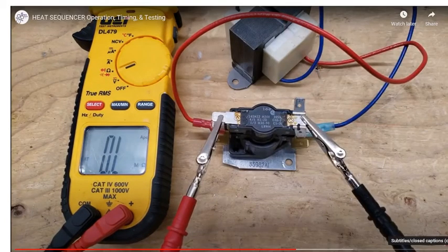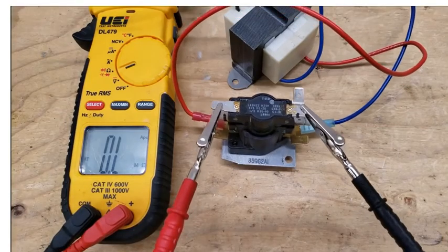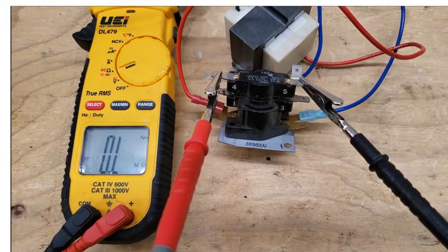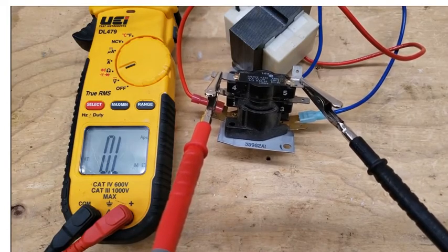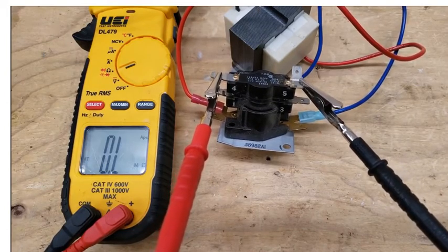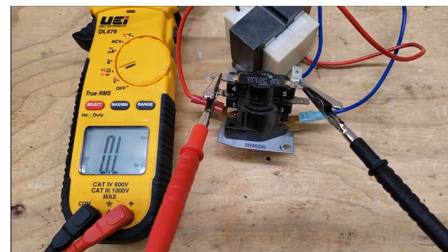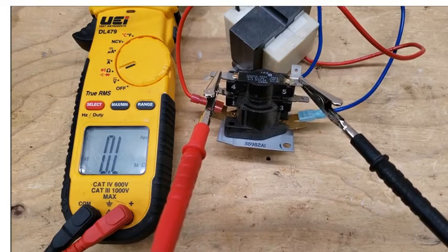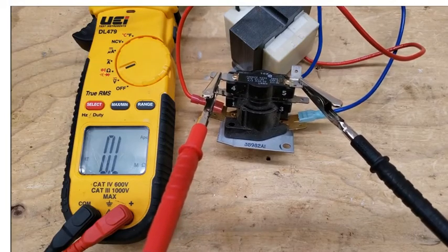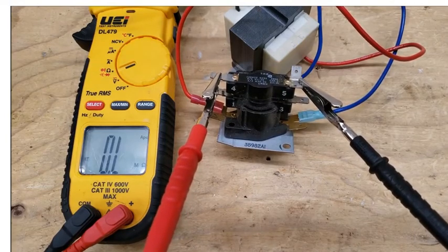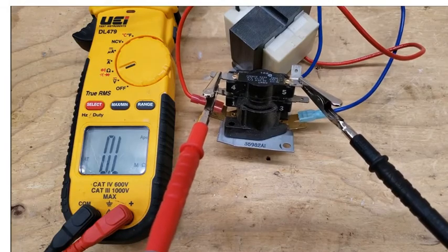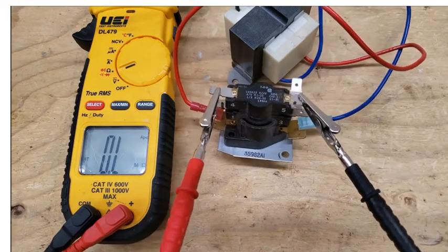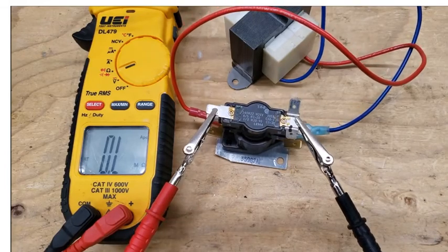In reference to troubleshooting the normally open sets of contacts, such as from 4 to 5 and 1 to 3, you're just going to go ahead and hook your multimeter up across those contacts. Make sure you disconnect your wires off of that first with the power off, and then you're just going to check this with resistance. So right now you see that we're reading OL, which means over limit or open line, and that means that those contacts are not connected. So we're just going to go ahead and time it to see how long it takes to close those contacts when we apply 24 volts to it.